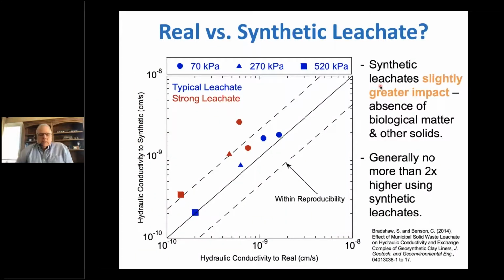Okay, I'm getting my test set up. I've got my specimen in the permeameter now. I've been careful when I put it in there. I've used non-woven geotextiles instead of porous stones. I put some bentonite paste around the edge. Maybe I put a little bit down around the bottom as well, around the periphery, just to seal that off. I'm ready to get started.